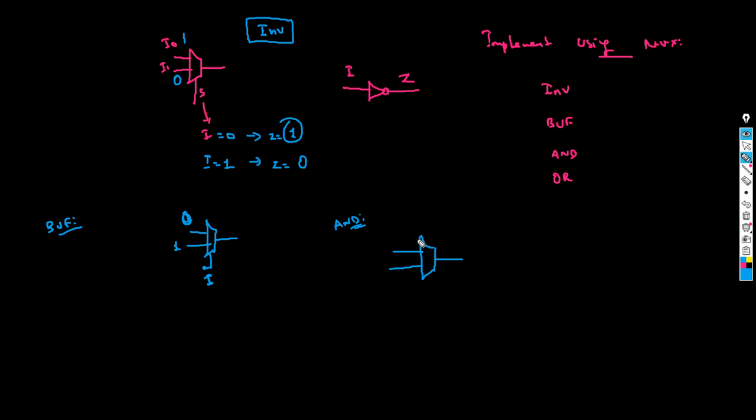The way I would always prefer is you having your truth table and all of that. So you eventually have to work it out that way, the process that I talked about. Remember one thing, the way we always do it, one of your inputs should always be the select line. Okay. So let's take A.